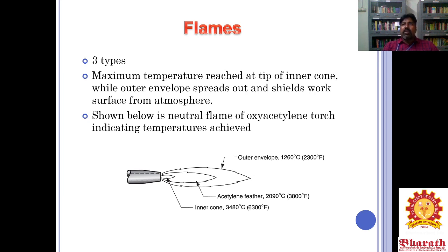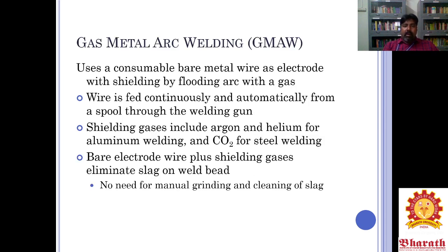It is not suitable for joining thick plates. Then it is a slow process. Then the strength of the weld is not as good as compared to arc welding. And handling and storing of gas cylinders need more care, and a gas flame may take more time to heat up the metal than an electric arc. So these are the important points about gas welding.